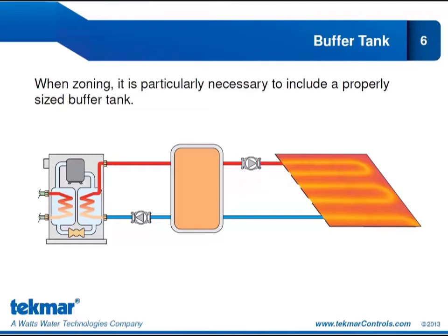In well-insulated and open plan houses, or if zoning is designed so that the minimum zone heating or cooling requirement is matched exactly or very closely to the minimum output of the heat pump, well, in that case, a buffer tank may not be needed. Also, heat pumps that have variable speed compressors may not require a buffer tank. So this is a general guideline, but depending on the heat pump that you have and the design of the zones themselves and the house plans, you may not need a buffer tank.